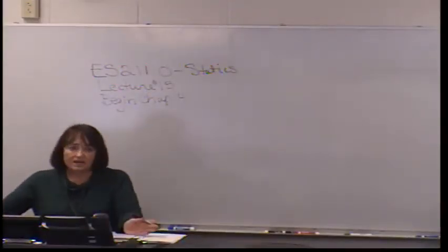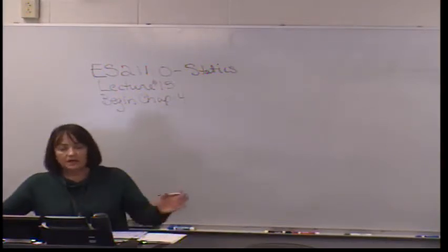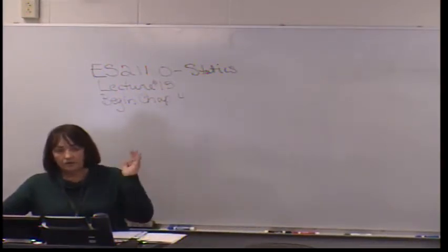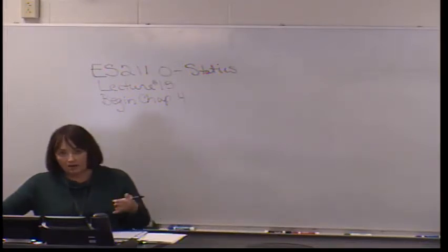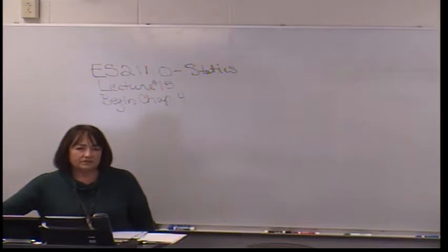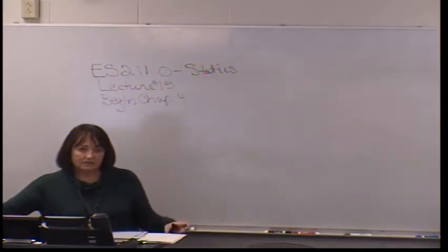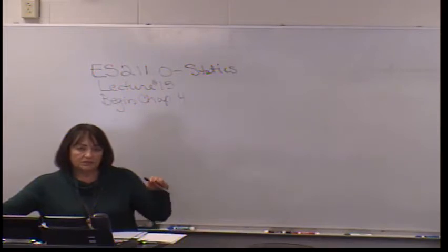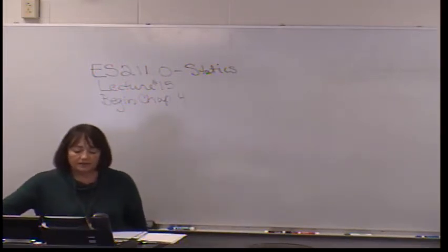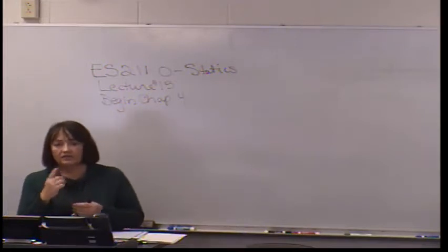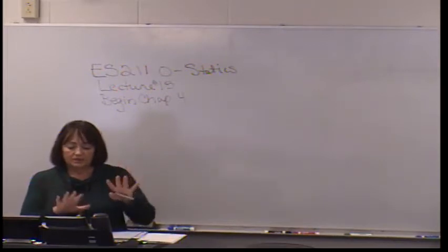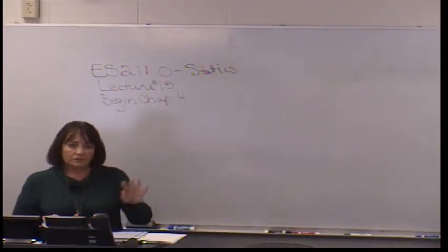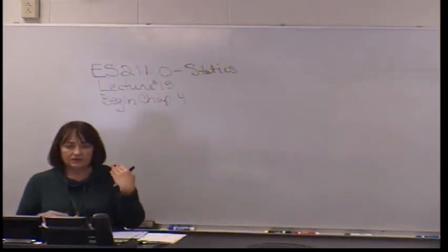All right, everybody, so that should get you going on the homework problems. All of the technique that we have used to this point in terms of finding forces and moments and resultants will all come into play in Chapter 4. The only piece of information we need to add is the idea of equilibrium of moments. Moments have to equal 0 on that rigid body. So in 2 dimensions, we only have one moment equation, which is perpendicular to the plane that we're working in. So if you think about the board or the piece of paper as being the XY plane, we only have the moments in the Z direction summed to 0.